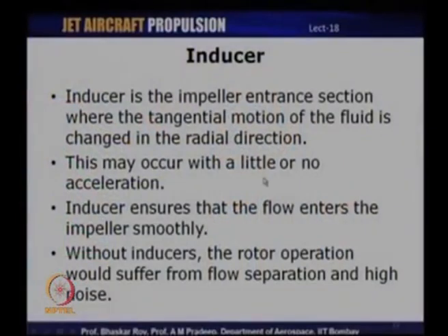So, the inducer is the entrance part of an impeller, where a tangential motion gets changed into a radial motion, and this may or may not occur with acceleration or deceleration, depending on the geometry of the inducer itself. The basic function of the inducer is that it should ensure that the flow enters the impeller smoothly, and therefore, without inducers there could be flow separation and high noise which might affect the performance of a rotor.